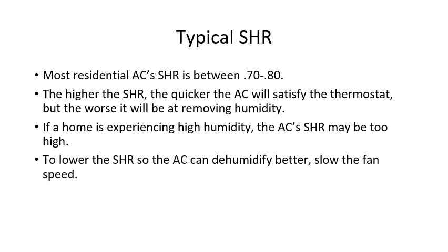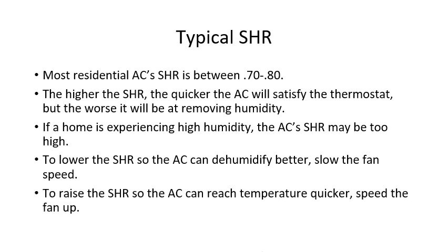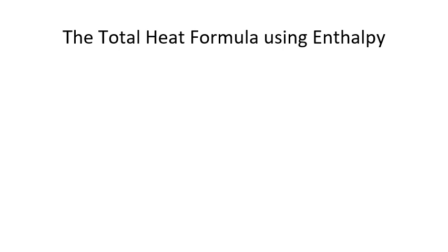So what can you do? Well, in order to lower that sensible heat ratio or make the system better at dehumidifying, you can slow the fan speed down. To raise the sensible heat ratio so that the air conditioning can reach temperature quicker, we can speed the fan up.